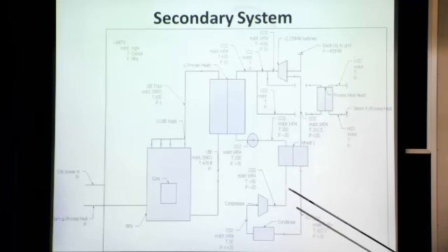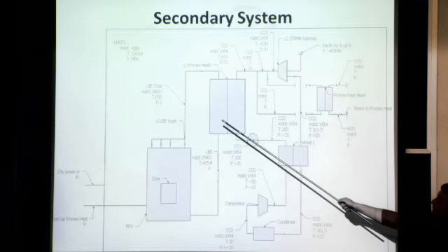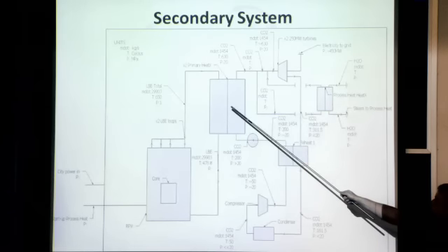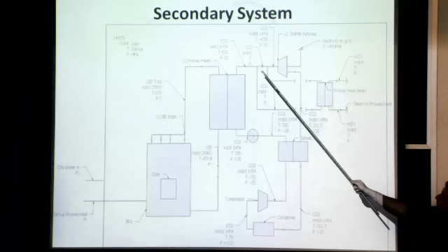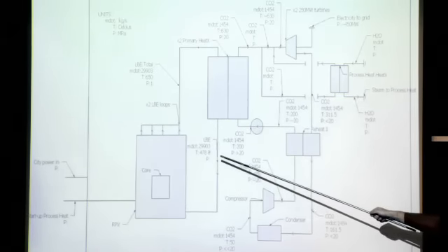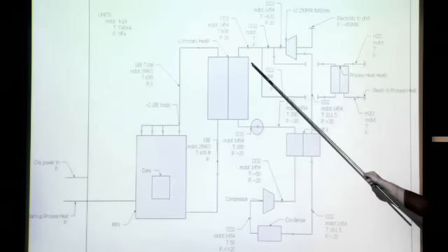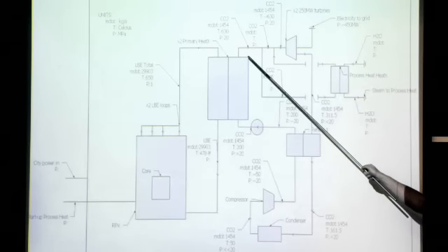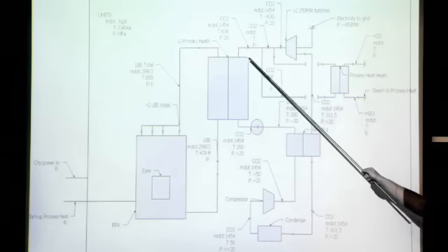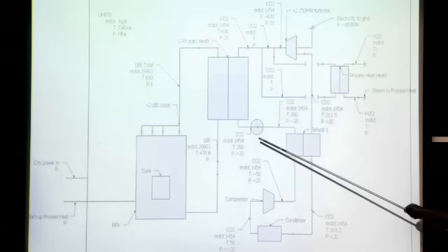Our first assumptions are 650 degrees Celsius out of the reactor core into the primary heat exchangers, as well as their output of 478.8, which is a calculation we did by hand as a rough estimate. Coming out in the CO2 loop, we can see 630 degrees Celsius coming out towards the turbine, and going into that we used 200 degrees Celsius.